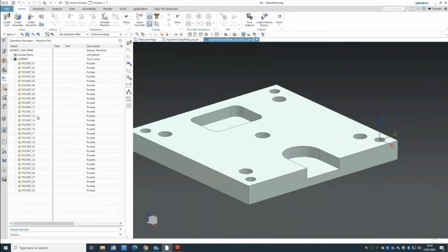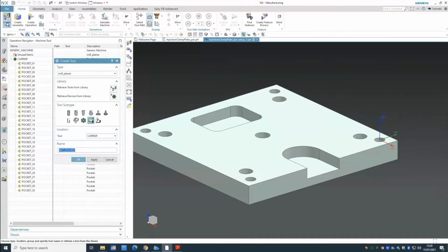So for instance, in your case, you can try that one, but because you already have these, I'm going to move on. I'm going to wait for the first operation to do. As Jeff and Charlie mentioned, we're going to use the face milling. In order to do the operation, I have to tell the machine what tool is required. So I'll go to the create tool, and I will make sure I'm in the milling first. And then I have to think about whether I want to have my special tooling or whether I'm going to use the standardized tool. There are pros and cons for that.